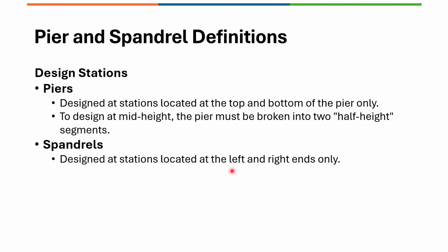The catch here is the diagonal reinforcement, if required, will be calculated for each segment, which will not be correct. So in that case, when you're breaking it for other reasons that force variation is necessary, then you'll have to manually calculate the diagonal reinforcement.